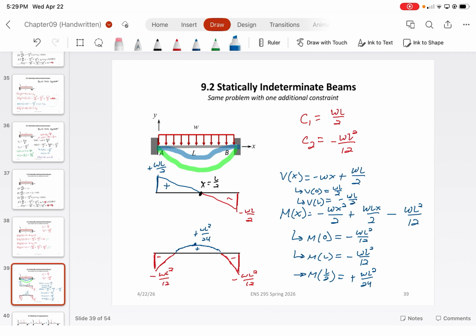So that's really the important aspect of it. And one thing you'll notice is that by using a fixed support, although it induces more load into the structure, it reduces the overall deflection because of the additional constraints. Make sense?